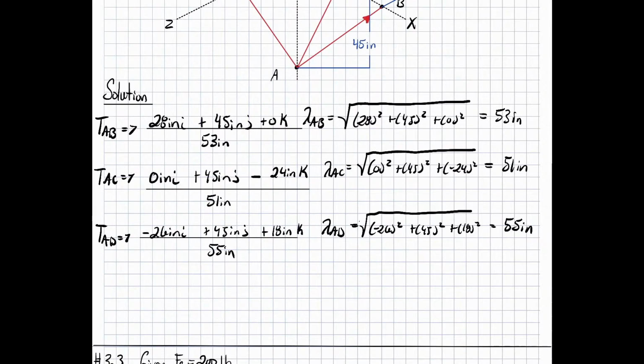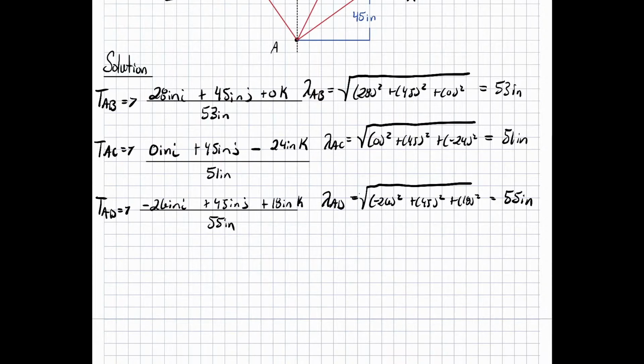Okay, so now we have our evaluations. We need to do our sum of forces. So sum of forces in the X direction, all equal to 0. Normally this is where you'd state your coordinate plane, saying like it's positive to the right or positive up. This is in 3D, and they gave us our coordinate plane, what's positive and negative, so we don't necessarily have to do that. But if you really wanted to and be more in detail, you could say that's positive down to the right.